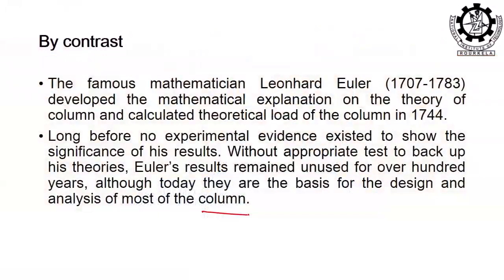Now, 100 years back somebody gave the experimental part, 100 years after that somebody gave the theoretical analysis, and again after another 100 years, this Euler formula, which is the most important formula, is utilized to analyze any kind of design. If there is a column design, Euler's rule has to be implemented first to find the critical loading of any column or strut. Euler buckling load or Euler crippling load, in our mechanics of materials, we will talk about the crippling load and buckling load. Now we are not going to discuss it.